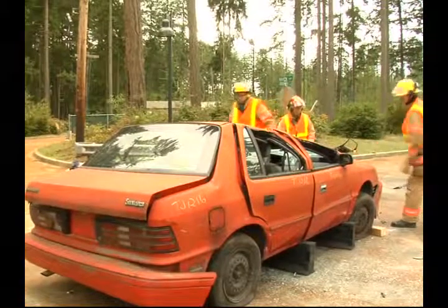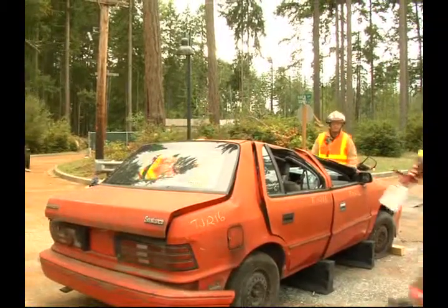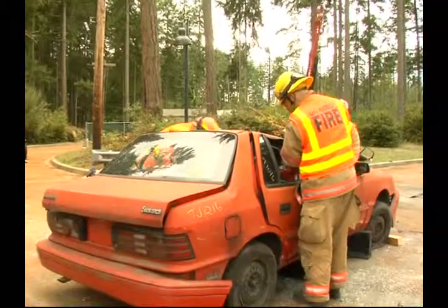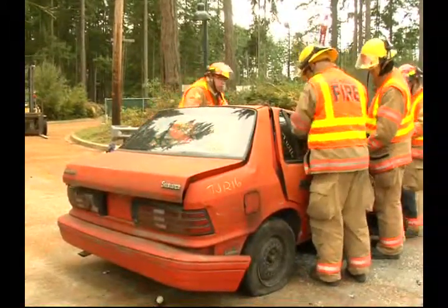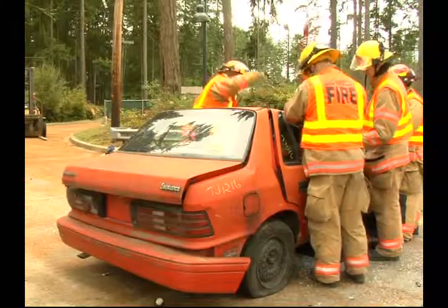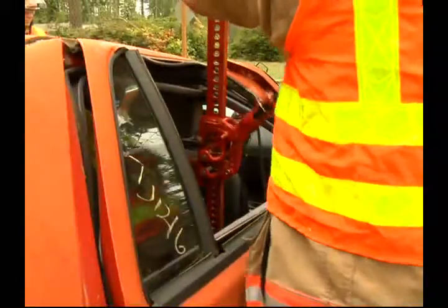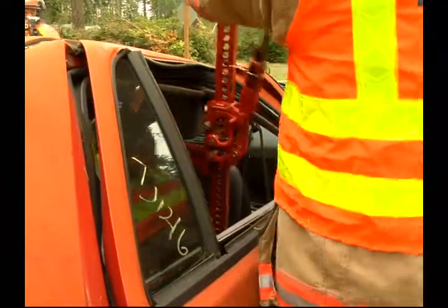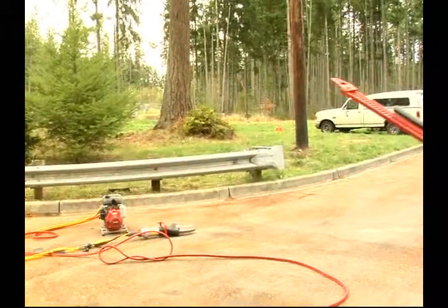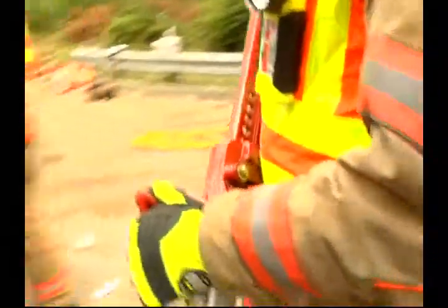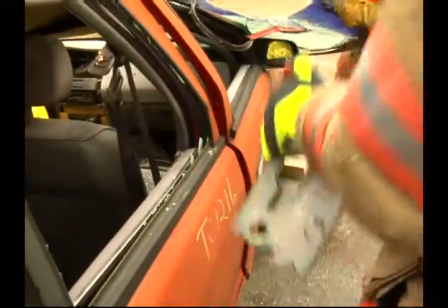Once the belts are cut, you can move on to the crushed roof. If the edge of the roof is crushed, a lifting tool can be used through a window to lift it up and return it to its original location. A manually operated tool that works well in this situation is a manual jack. Place the base plate on the bottom of the window opening or inside on the floor of the vehicle closest to the door.